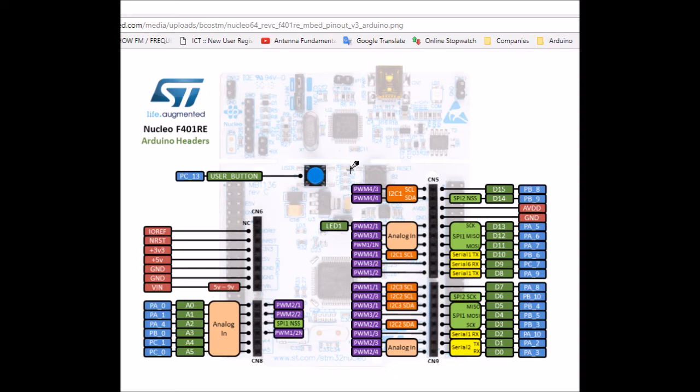And in this video, I want to show you how to use ADC in continuous conversion mode, where ADC will continuously acquire and convert data, non-stop, unlike the single conversion where we trigger it if we want to get a conversion and it will go to sleep. But here, the ADC will continuously convert data and send them to memory.